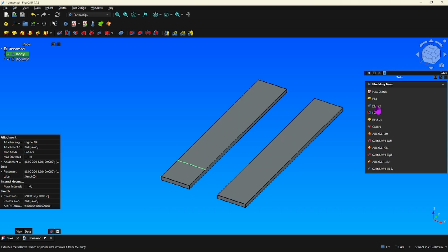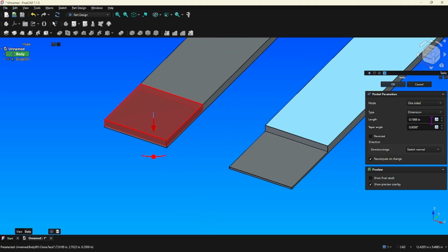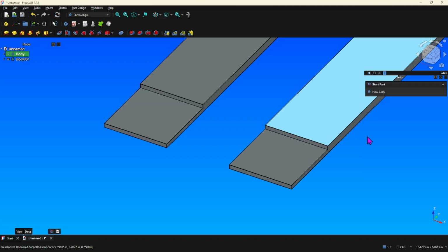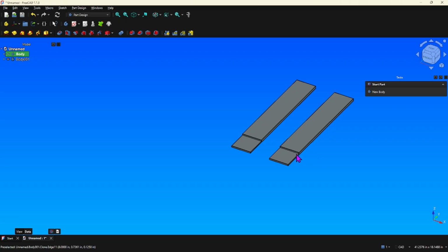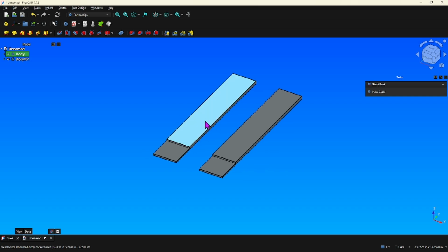And we want to put a pocket. And we want the depth of that pocket over here, the length, to be 0.125, and I'll select enter. So there you have it. What you did to this piece here, the clone will also change because it is relative to this piece now. All right, so now we just need to transform this piece, get it into place.